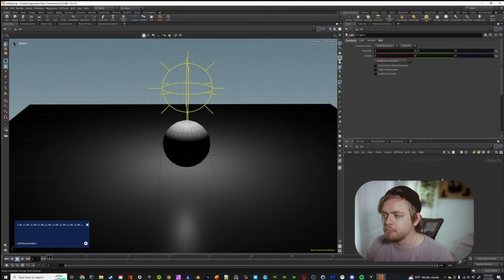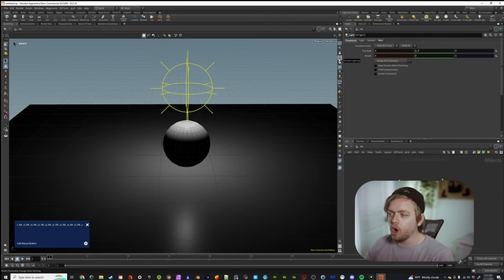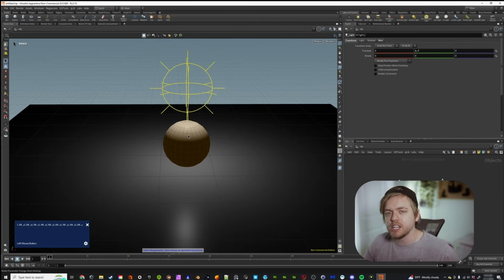Essentially, the very bottom here is disable lighting. This is not disabling your lighting in your scene for the render. It has nothing to do with that. I want you to separate those things in your mind. This all pertains, all down this side, only to what we are seeing in the viewport. It's all temporary. It's all just servicing us building the scene, and that's it. It doesn't go any further than that.